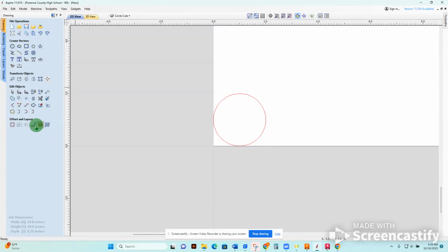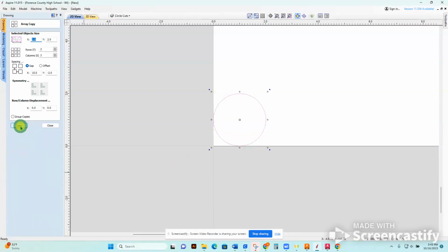I'll close. I'm now going to choose that piece. And if I wanted to make a bunch of these, I'm going to use the array tool. And I'm going to go with 6 columns across the X. If you're confused about what X and Y are, you can move this around and see. You can also use that hand trick that I've shown you. So there's column X, there's going to be 6, and rows Y.